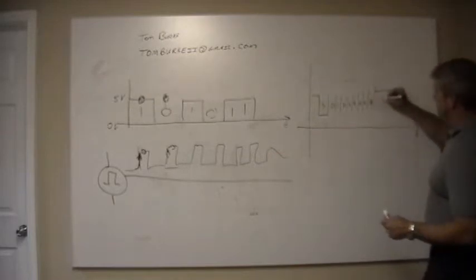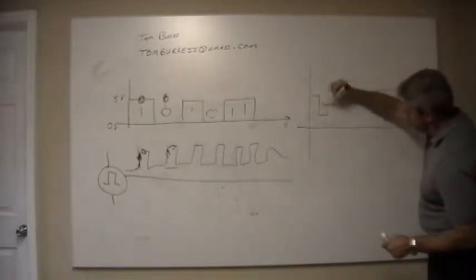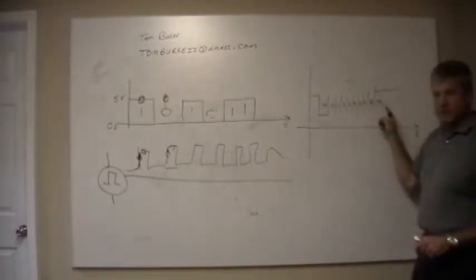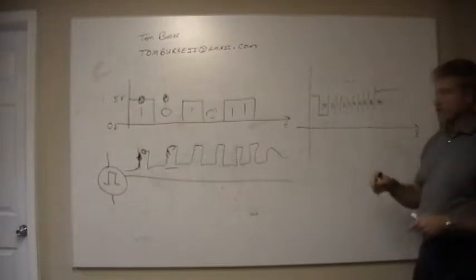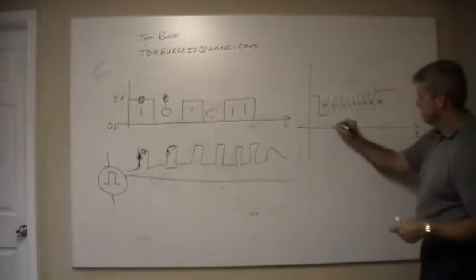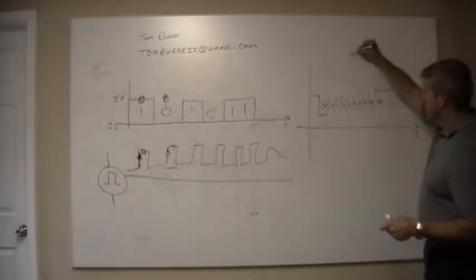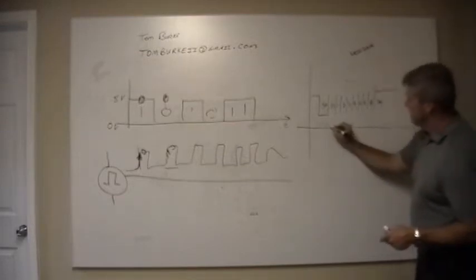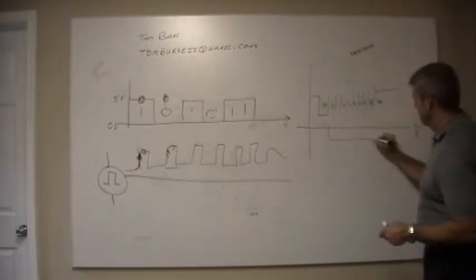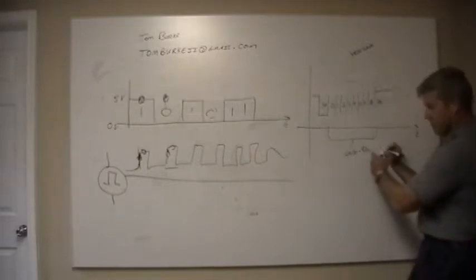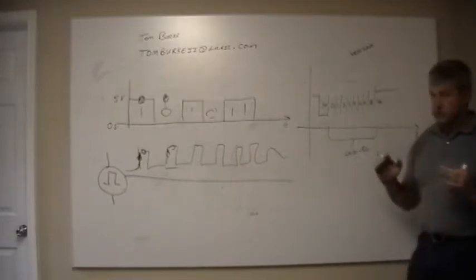So this start bit and stop bit, these are overhead. So for me to send 8 bits down the pipe, I actually had to send 10. My baud rate, if I'm doing 4800 baud, says that I am doing 4800 times 8 bits, small b, of usable data.